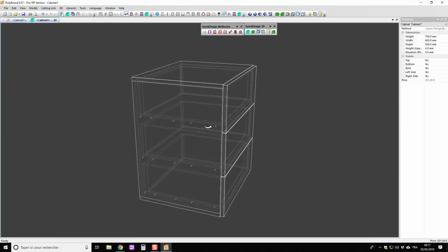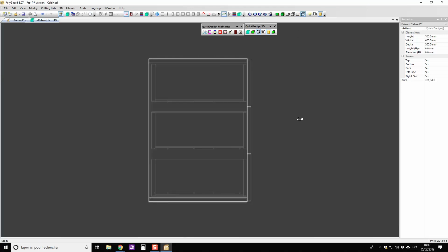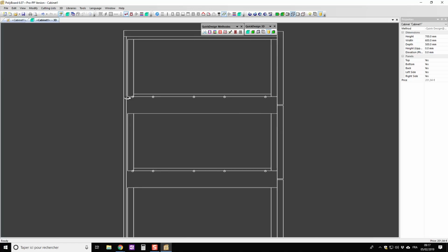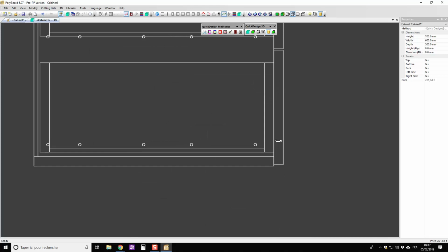They've been drilled in place as if normal, but if we look carefully, like if we look at an orthogonal view and we look face on, and we can look at our fittings, and let's make them a bit more visible, we see the holes here have been drilled in this position, and they're relative to the drawer bottom, just along the drawer bottom. This second drawer is the same, but if we roll down here, we can see that these ones are not the same, and this is because we are actually calculating the position of these drillings using the rule that was set for the normal drawer sliders, which was calculated from the drawer positions according to the zones.